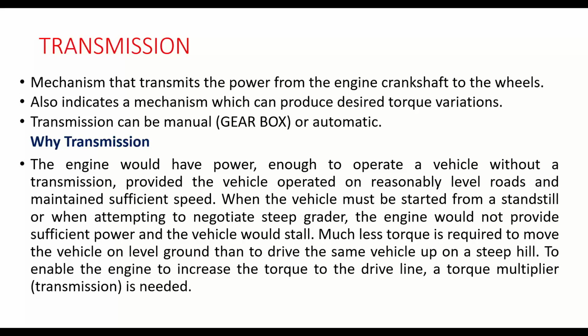At which gear can the vehicle run comfortably? For example, if you want to initially move the vehicle, you cannot move it in third or fourth gear. A huge torque is required. You have to put it in first gear, where huge fuel will be consumed, but torque multiplication will be more, and the vehicle can start moving. Once it picks up the speed, you will switch to the second, and so on. So transmission can be either manual or automatic.